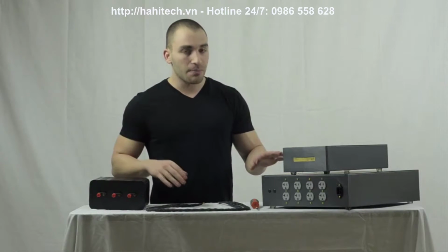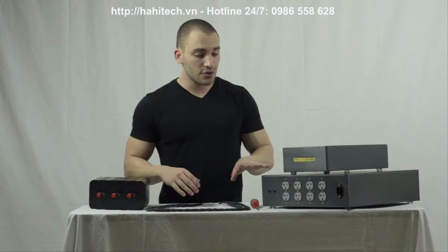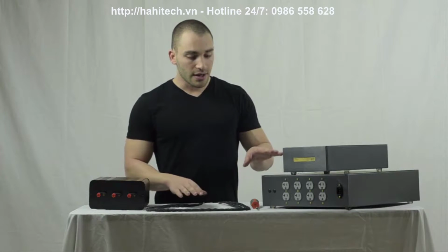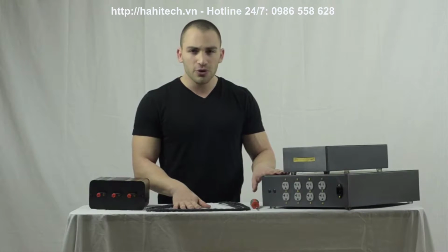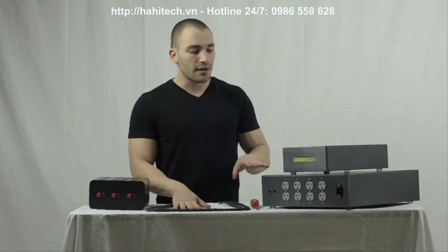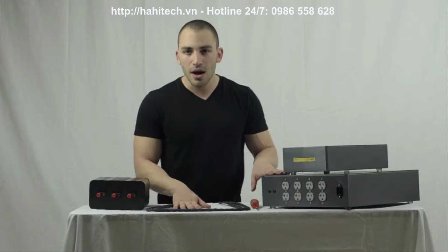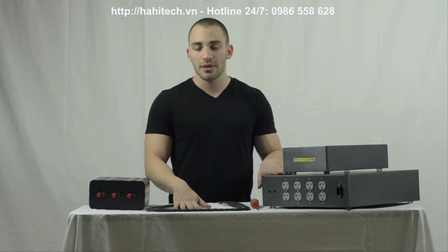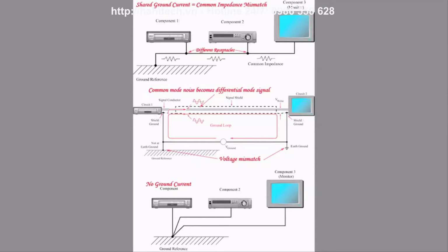I'll be talking a little bit about audio system grounding and give a few tips and tricks for troubleshooting grounding issues, as well as understanding where grounding issues come from in the audio system to begin with. Generally what happens in an audio system is you have different ground voltages from outlet to outlet. And this is the case whether you have your audio system on dedicated circuits or on a single circuit but different outlets.